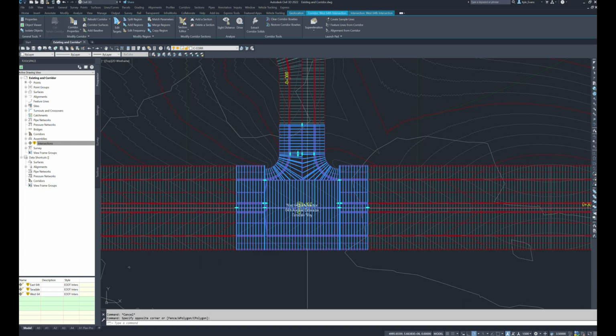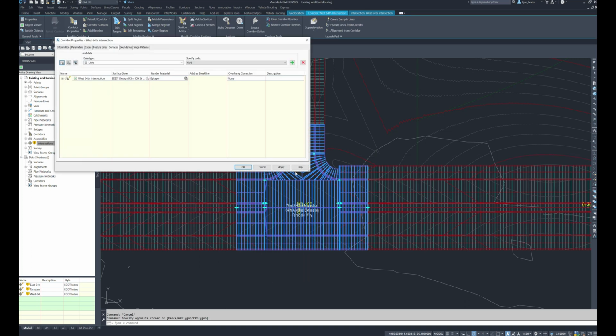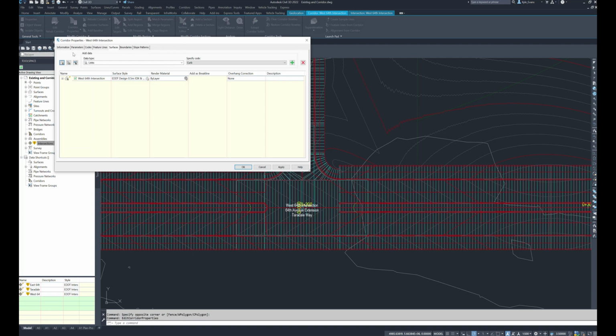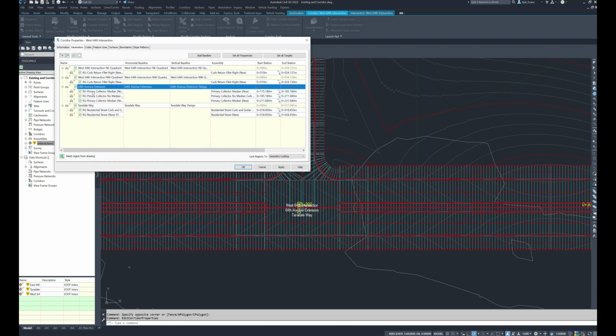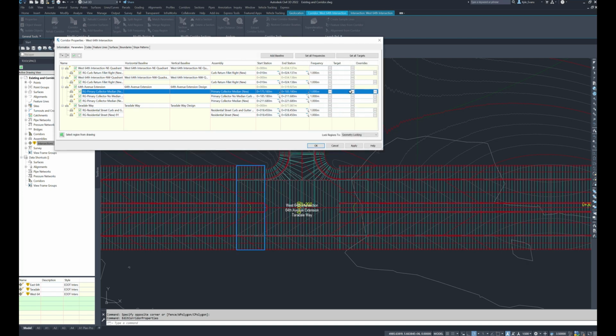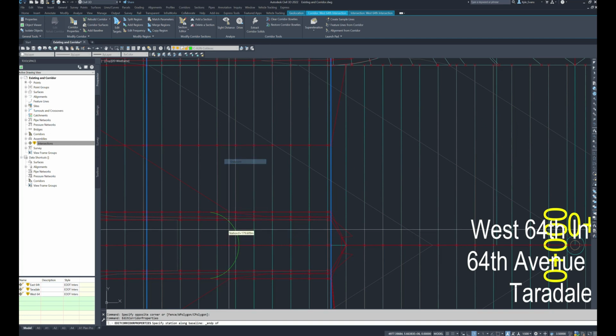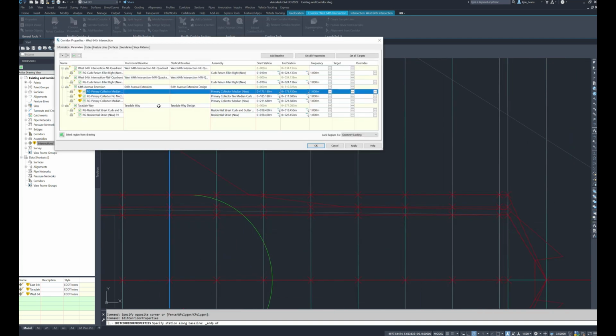So again, we did this in the previous video. We're just going to do it again quickly here, just for more practice. The thing with Civil 3D is practice, practice, practice. So I'm going to change the start and end stations again, and move the median back to the end of that bull nose. So I'm just going to adjust the end station for the road with the median. I'm going to insert a region after with that primary collector, no median.